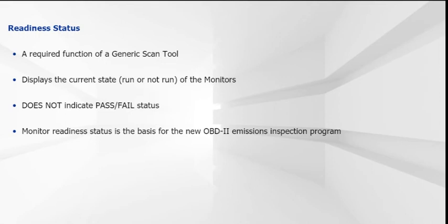Monitor readiness status is an indication of whether the PCM has tested all of the vehicle's emission controls. In states using OBD II IM, that's inspection maintenance test programs, one or more monitors displayed as not ready may cause the vehicle to be rejected for the test.